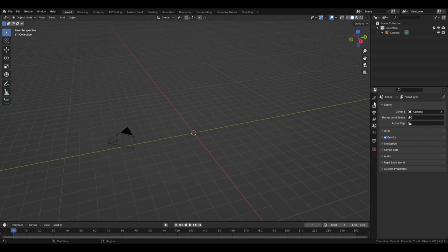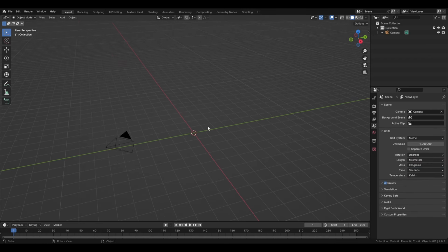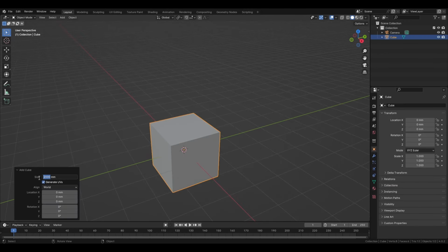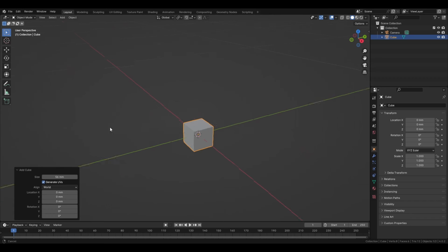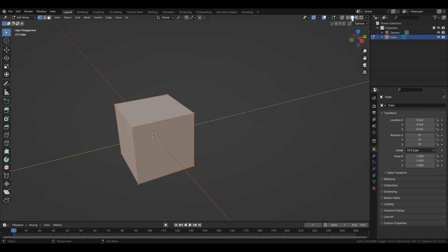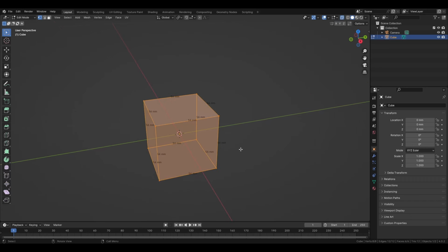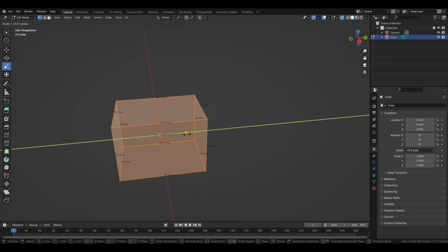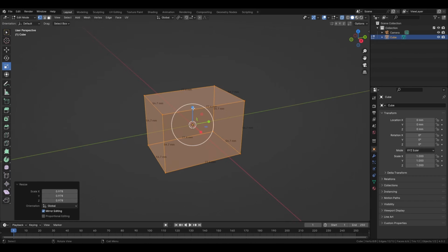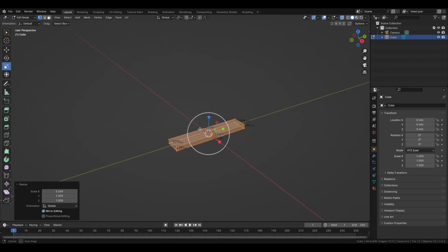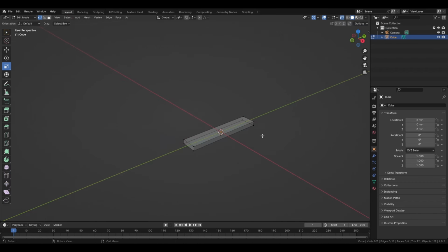We're going to change the units of the scene by going into scene units, setting them to millimeters. Then we want to create a ring which is 18 millimeters, so it's going to be roughly 60 millimeter diameter. So we're going to create a block which is 56 millimeters wide. You can go into edit mode, put the edge length, Alt Z to have it transparent. Select everything, and we want it to be slightly longer. And here we want the ring to be thinner and narrower, so like this.